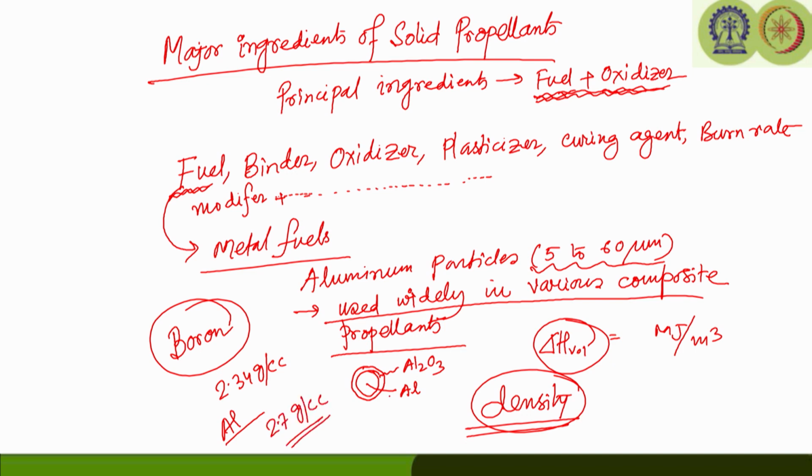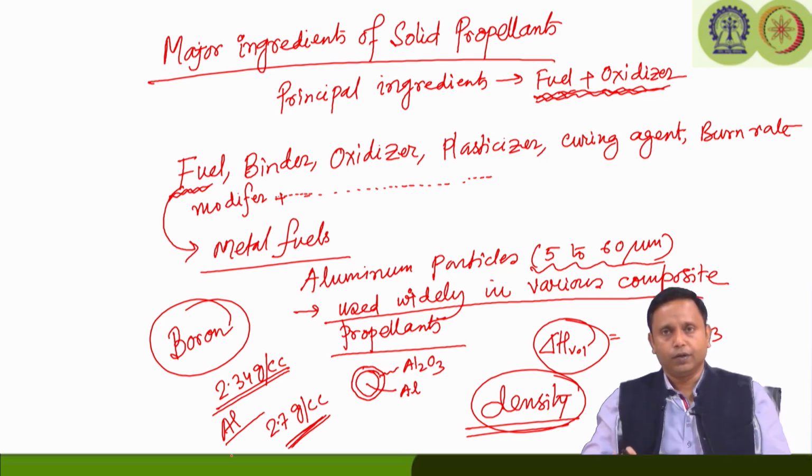So, from the choice of the higher density of propellant, definitely the metallic fuels are giving the advantage compared to the normal hydrocarbon fuels. But the problem is how to burn the metal fuel efficiently. So, the deficit lies in that efficient combustion of these metal particles is not properly done. If they are not burning properly, the utilization of the energy is not very efficient.